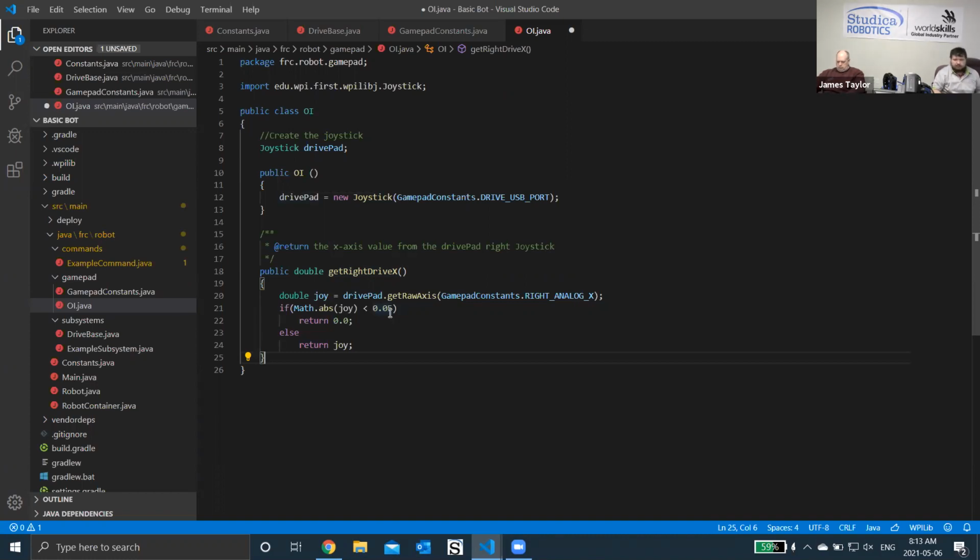The reason we have the dead zone is that not all controllers perfectly snap back to 0 on the joystick. So we create a dead zone so that when it snaps back to its home location, if it's slightly off, it's still reporting 0 back to the controller. This reduces any drift. Right now I have it at 5%. Some people might extend it to 10%. It's up to you. You can adjust it.